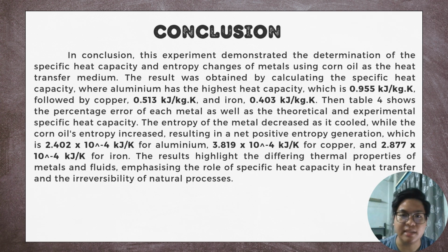In conclusion, this experiment demonstrates the determination of the specific heat capacity and entropy change of metals using corn oil as the heat transfer medium. The result was obtained by calculating the specific heat capacity, where aluminum has the highest heat capacity, which is 0.955 kJ over kilogram times Kelvin, followed by copper 0.513 and iron